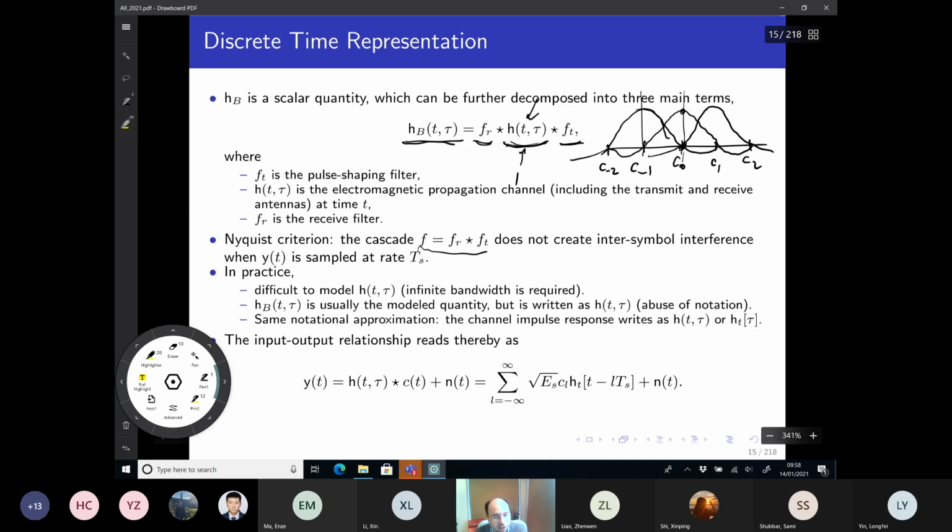If you have echoes against a wall, against a mountain, against a building, that will impact the shape of this H here. I won't have just a 1. I may have echoes that look like delay profiles. I may have some echoes like this, and some of them may be stronger than others, depending on the propagation conditions.